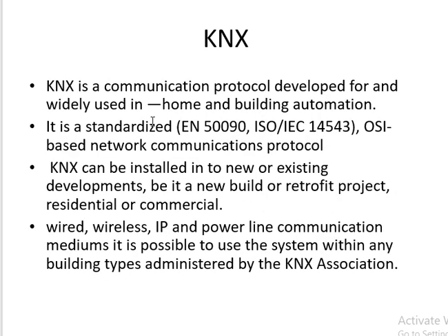So KNX is a communication protocol widely used in home and building automation. It is a standardized and OSI based network communication protocol. KNX can be installed into new or existing developments, be it a new build or retrofit project, residential or commercial. With wired and wireless, IP and powerline communication mediums, it is possible to use the system within any building type, administered by the KNX Association.